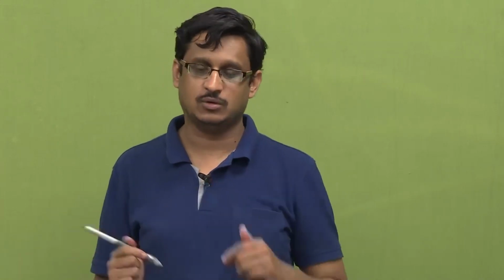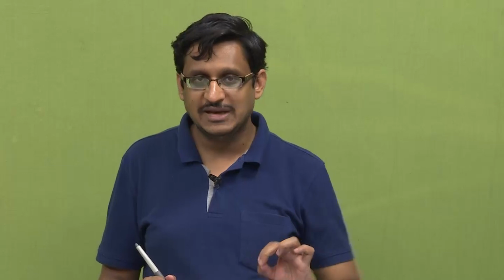So, you send in say 1 milliwatt and let us say you get 1 milliampere of current, then the responsivity of this device would be 1 ampere per watt. Of course, it does not mean that you can just take 1 watt of optical power and expect 1 ampere of current. Maybe the photodetector itself would break down when you start putting in lots of power. So, it is not a linear relationship, but the units are always measured in terms of ampere per watt. In most communication photodiode receivers, the unit is milliampere per milliwatt, indicating that you are working in the milliwatt region of optical power, and the currents that you generate are in about the milliampere range.